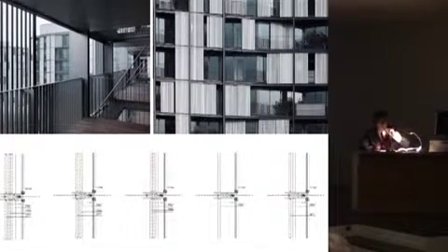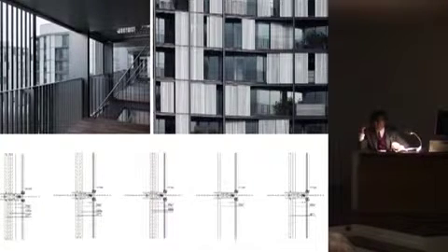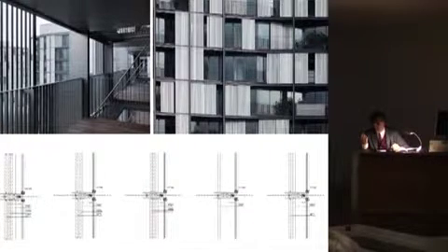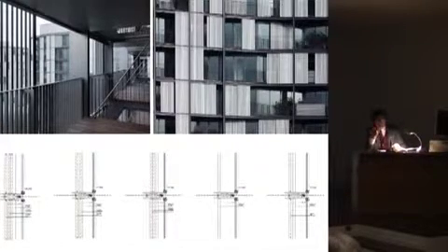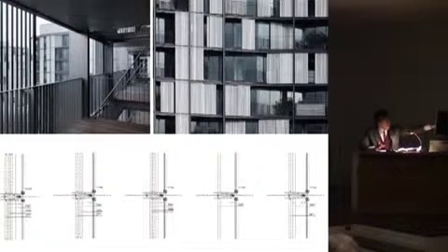Here you see the details, see the drain pipe, you know, there are terraces there, and where does water come down from? I mean, you take the water to the inside of the flat, or you tilt it to the back, and maybe water enters the parquet floor, and you let it drip, or maybe you let it drip on the facade. No, you cannot do that.